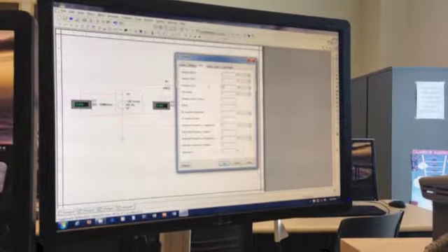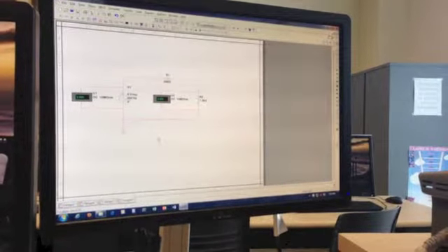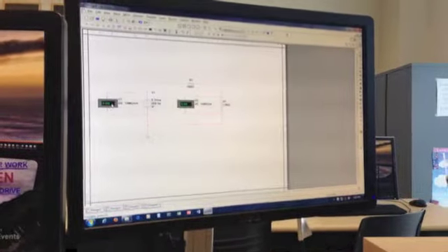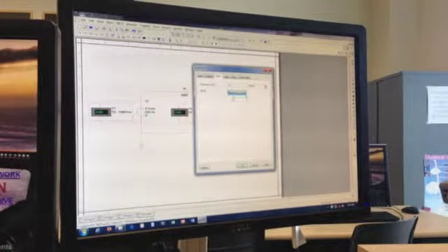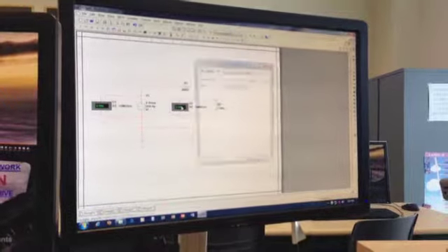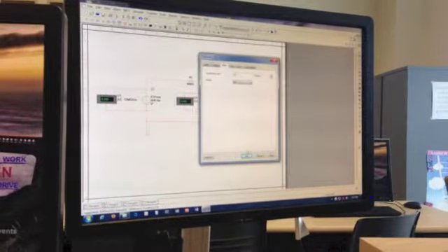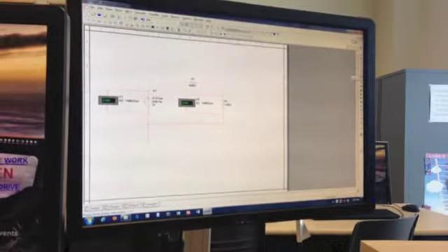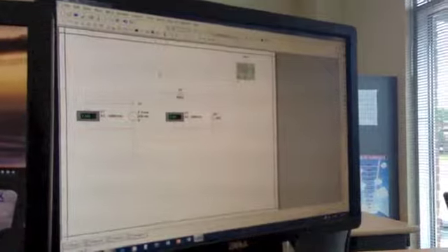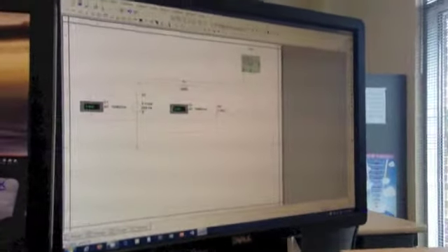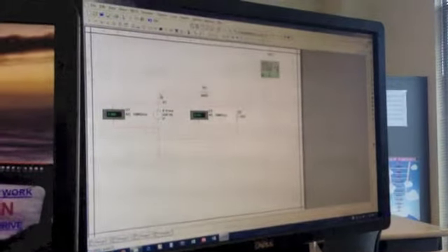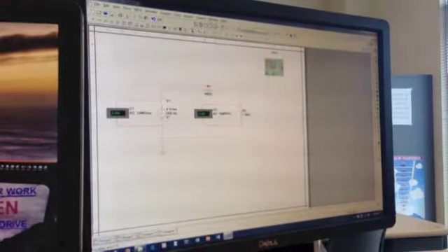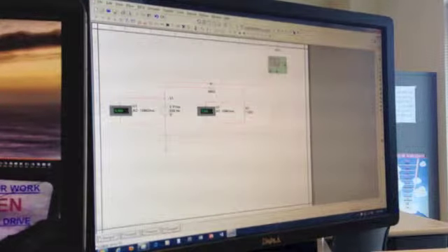Frequency was 200 hertz. So we'll set that, and then we will change these to AC because we're measuring alternating current. From there we will add our oscilloscope so we can measure frequency and time. We'll connect channel A to the source and to the ground.